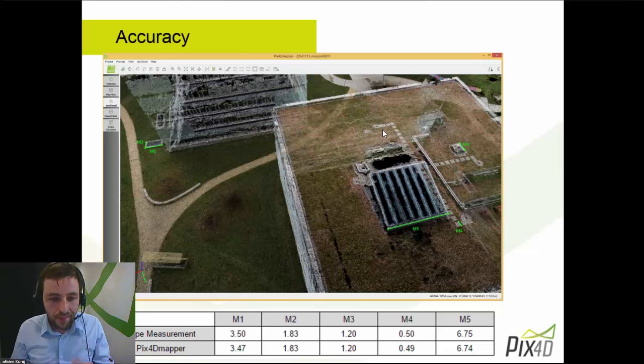But on the other hand, if you would take a professional GPS, take 3 ground control points in this data set and introduce them in the software, then you would very likely be able to have a centimeter-like accuracy, absolute global accuracy for this project, which is very impressive.